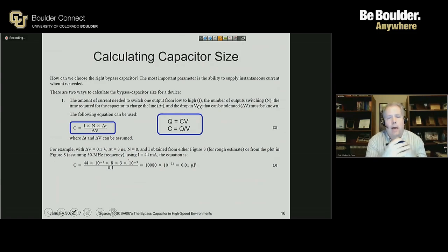And what happens in the design is that you can set these capacitors up on your board in such a way that there are high frequency capacitors near each chip, and then there are these bulk decoupling capacitors, which may be located further away from the chips, maybe close to the voltage regulator or power supply, and they work together as kind of a bucket brigade.